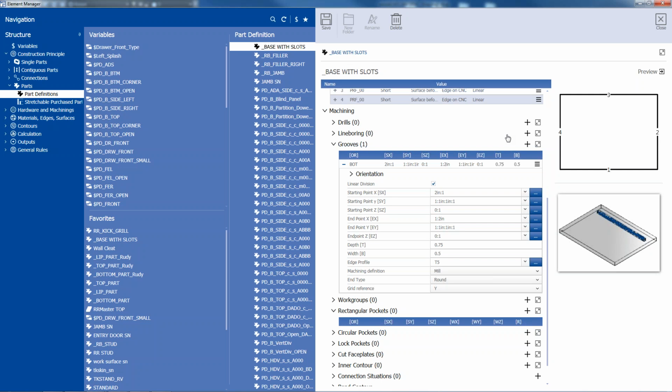Why is that then? Because it's a front, it's rotated 90 degrees to the right, laid on its side. So this is actually the bottom, this is the right side, this is the left side, this is the top. So since it's a vertical grain, it's a front, so you know your X is actually this way. Y is this way. Trust me, just flip these values around. Part definition is based on how you use it.